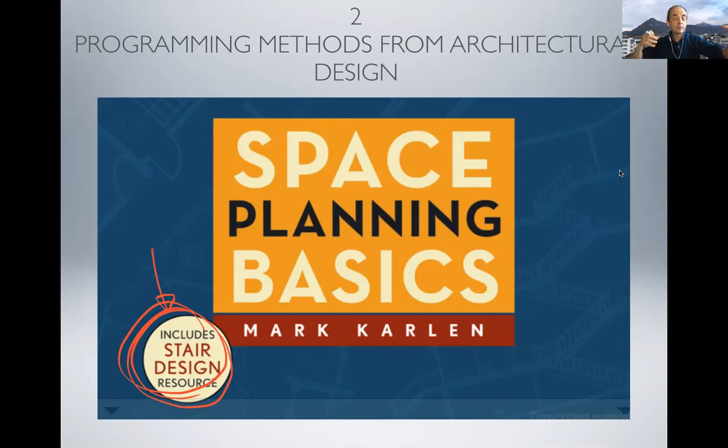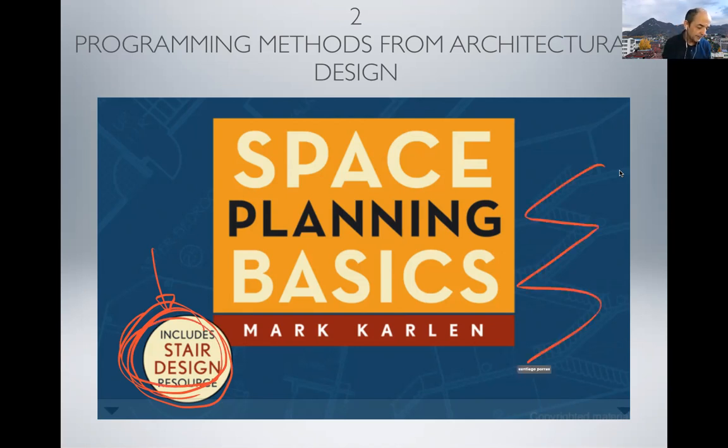You cannot have too many stairs in a building. So the correct position and size of one stair is critical, and that will make your design much easier, or much more difficult, or totally impossible in some cases. The stair and elevator, of course, go together. This is part of the same vertical communication. So if you see this in the building, you can see how important it is. And actually, it is part of the illustration of the cover.